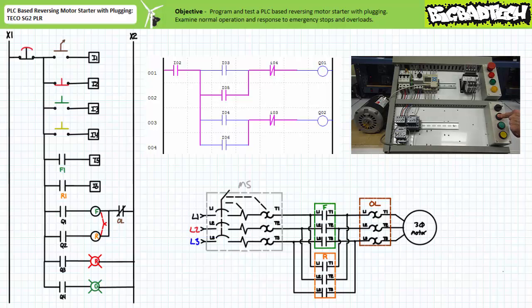When the stop button on input 2 is opened, the forward contactor coil is de-energized, the forward primary contacts open, and the motor turns off. You note that the make instruction examining input I5, the F1 auxiliary contact, confirms the forward contactor is now open and drops the holding circuit. This system behaves as anticipated for normal operation.